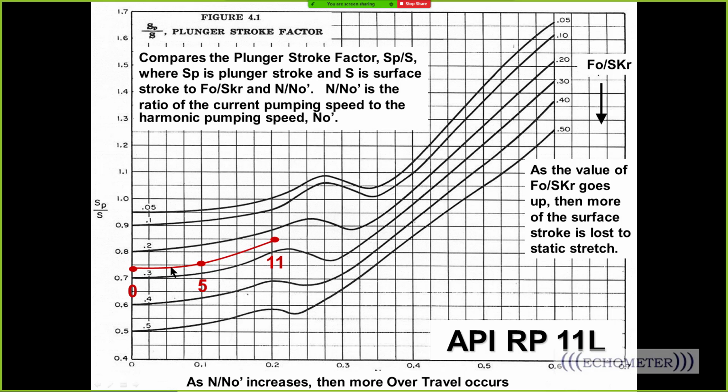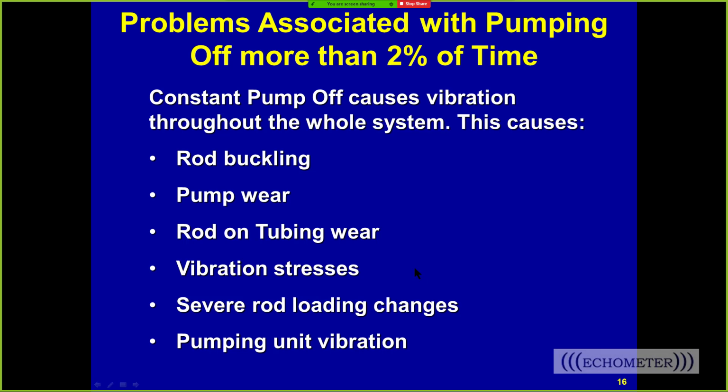And what I wanted to show is that when you run Q-Rod, it matches what we used to use by hand of the change in the downhole stroke compared to the surface stroke, that's the ratio of the pump stroke to the surface stroke. Q-Rod would match and calculate the same thing that we would calculate a long time ago, based on this nomograph that we'd created a long time in the past.